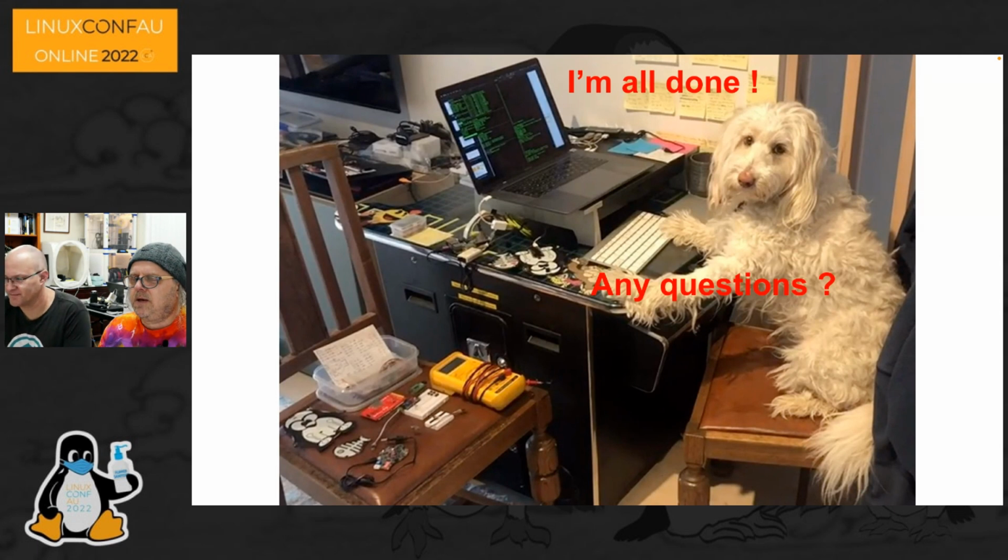Okay. Let me think about this a sec. So the wishbone bus allows you to wrap any peripheral in the FPGA on a 32-bit address. And so what we could potentially do, and I'm really making this up on the fly, is we communicate between the ESP32 as the I2C controller of bus 0 and the FPGA as the peripheral.